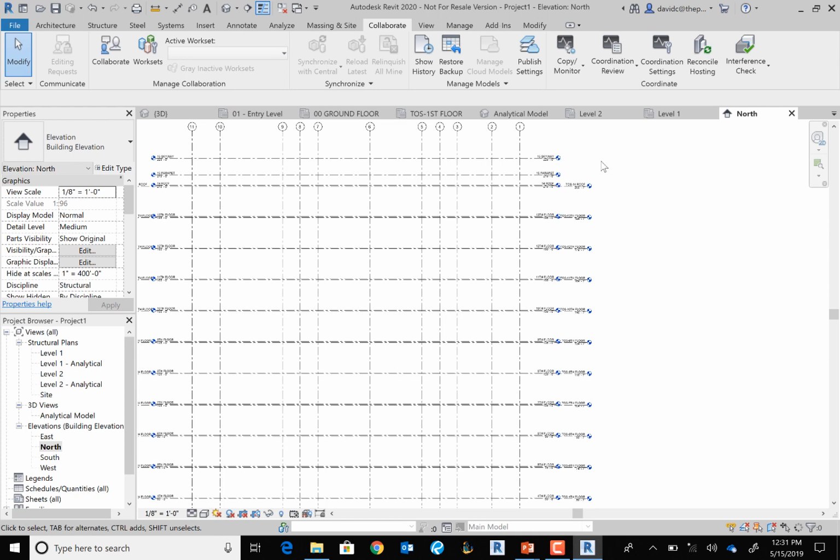And as you're going through modeling for structure, that's when we're placing our either structural steel columns, or we're placing our tops of footings, or concrete walls, concrete columns, what have you, okay? Then from there, I would go ahead and probably on BIM 360 Design, push up this model and give the architect the rights to go ahead and view my model, right? So then they can link that in and they have an updated structural model, okay? And then just as it's going back and forth, that's where my model is living.